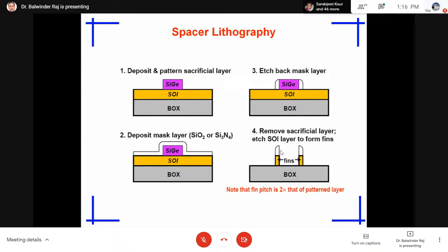If we have 5 fins, then the complexity is very high. Although they work well, people preferably use 3 fins for circuit design. Why 3 fins? Because, as I discussed previously, the parasitic capacitance can be removed automatically, and the fabrication issues are also a little bit simpler.